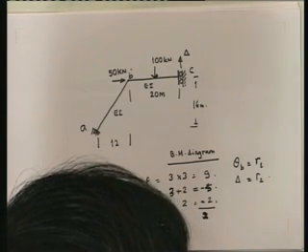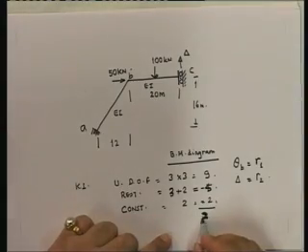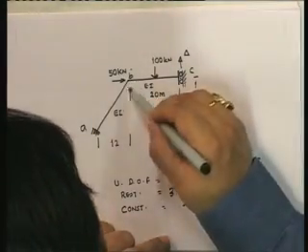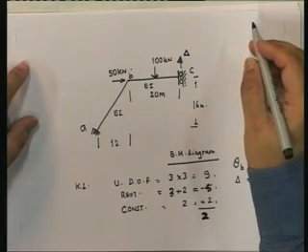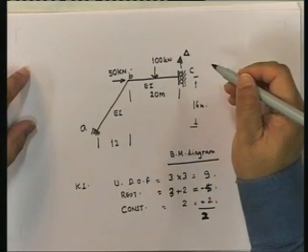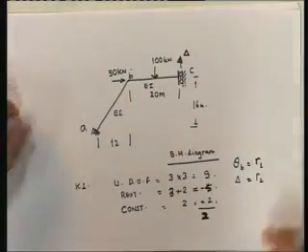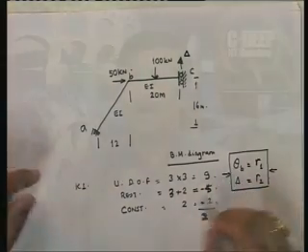Now, here the point to be noted is this. Let's look at this. Can this rotate? This can rotate. If this displaces upwards, what happens over here? If you look at it, this joint can rotate in any direction that it wishes, because AB is constrained to move. So you have 2 degrees of freedom. We have identified 2 degrees of freedom for this structure, and so we've completed the first 2 steps of the displacement method.